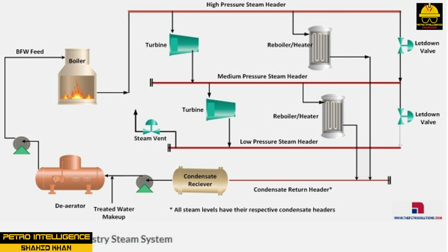Non-condensing operations utilize the exhaust steam in operations where lower pressures are required. MP steam is supplied partially by exhaust from small back-pressure turbines and extraction steam from larger turbines. In case of insufficient supply from the above sources, the letdown station between the HP and MP headers makes up the balance of steam required at the MP header.